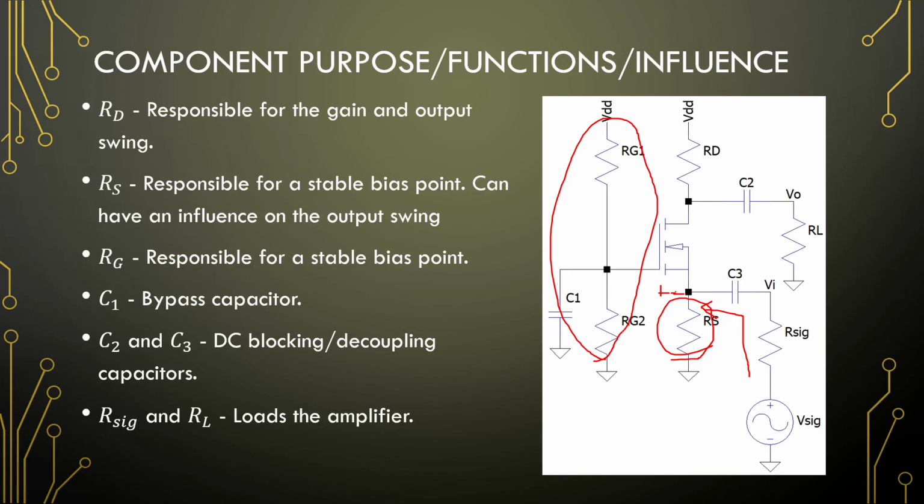And it doesn't matter what the values of these two resistors are. So typically you just have a specific amount of current that you want to flow through there, and you do your component selection purely on that. You can choose them as large as you want, since they only provide a voltage.